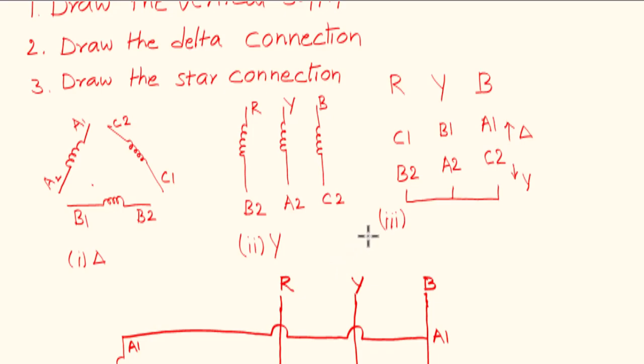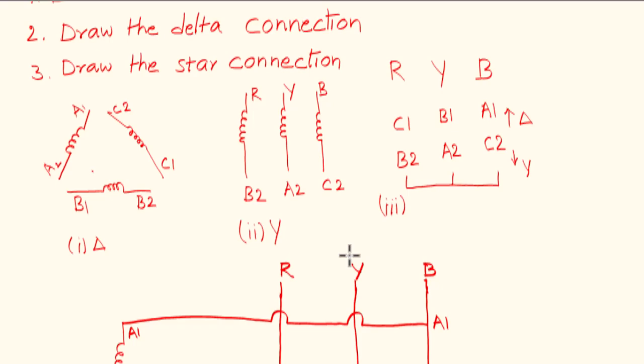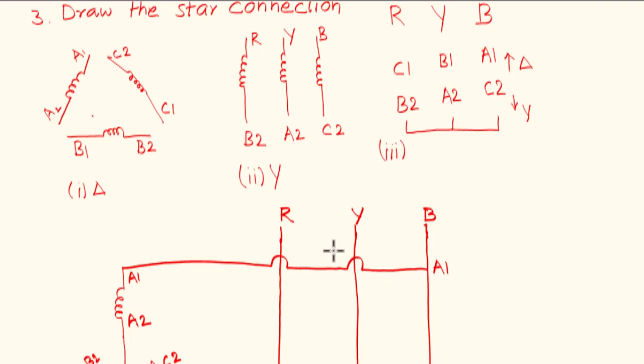Once we know this, it will be substituted in the full load torque and starting torque ratio, and then the simplified equation will give the starting torque in terms of the full load torque.